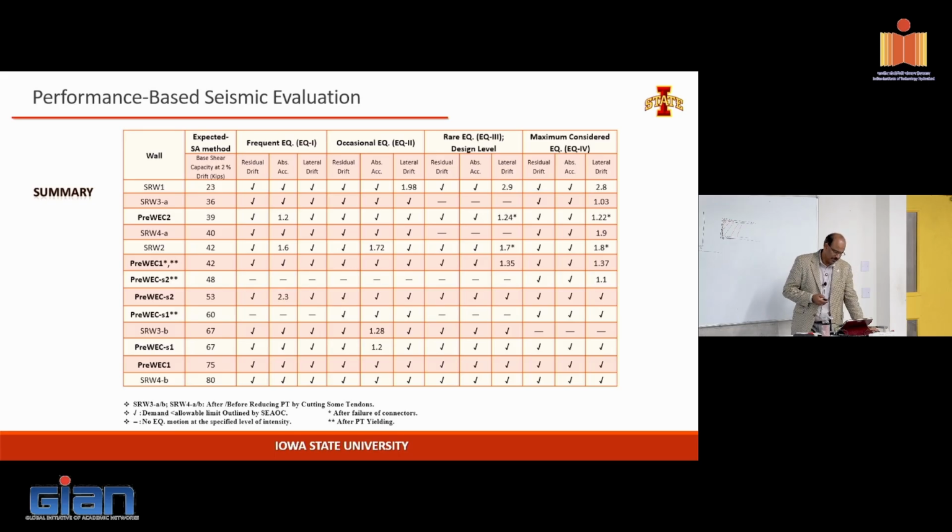The other variable we used was the maximum lateral drift, right? The structure may perform well, but if it's displacing twice as much, maybe that's not a good thing. Things are going to be thrown around and people may not feel comfortable. It could cause displacement compatibility problems for the gravity systems. So all of that stuff. For each case, we have a threshold value.